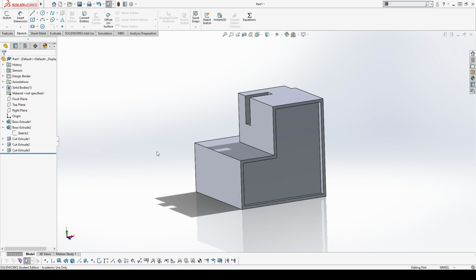And for those of you who weren't there in person, as an exercise, I strongly encourage you to go into our lab and just model a profile of a part. So maybe look at a wheel center and just draw it out in SolidWorks. And maybe take some calipers to it, add some dimensions, some relations. If the wheel center has some spokes, maybe do a circular pattern and try to figure out how to define that pattern to be a fully defined sketch. But that's just an exercise for you guys. You're welcome to shoot me an email or get a hold of me if you have any questions. But that should be everything for the second half.